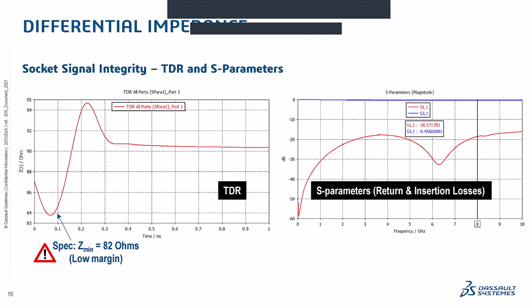We have very small insertion loss, less than half a dB across the whole spectrum, and the reflection loss is below 18.5 dB.